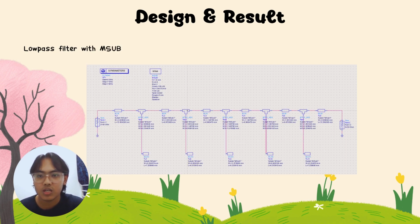Okay, next, we construct a low pass filter with MSUB. For the MSUB, the specification is already given in the report. And for this low pass filter, we use 6 MLIN, 5 MLOC and 5 MTEE. For the value of MLIN, we take the value from the microstrip fabrication on the upper part, and for the MLOC, we take the microstrip fabrication value from the lower part. For the MTEE value, we take W1 from the MLIN on the left side, W2 from MLIN on the right side, and W3 from MLOC from the bottom part. This process is repeated for the other MLIN, MLOC, and MTEE.